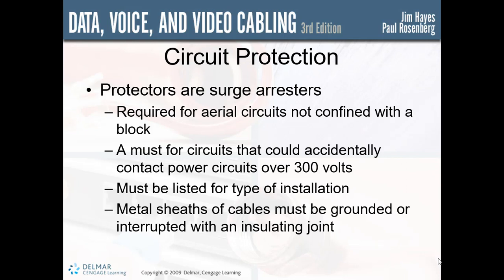Underground communication conductors must be separated from power conductors in manholes or handholes by brick, concrete, or tile partitions. Communication conductors should be kept at least 6 feet away from lightning protection.